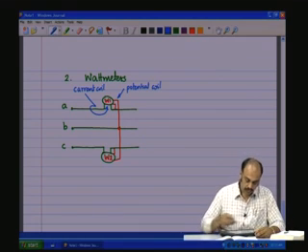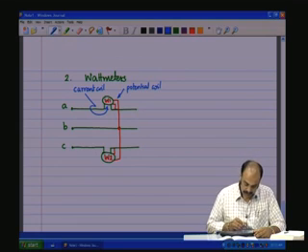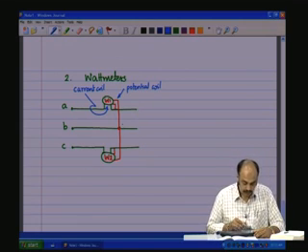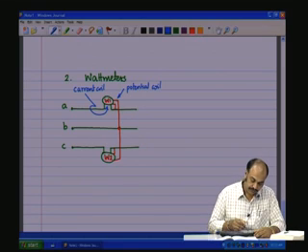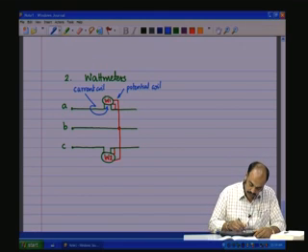Okay. So, the current of the A phase, current of the C phase is taken, the B phase is taken as the reference point, the potential of A phase with respect to B, C phase with respect to B is measured like that, and this of course goes to the 3-phase load.